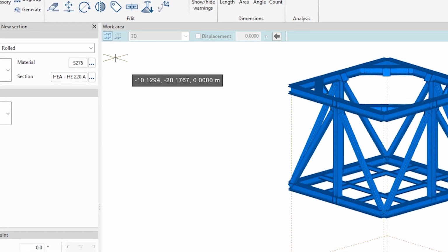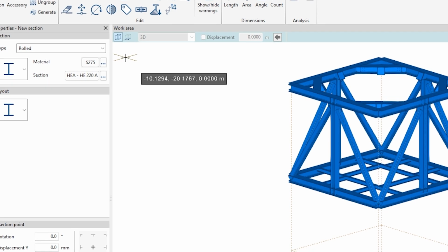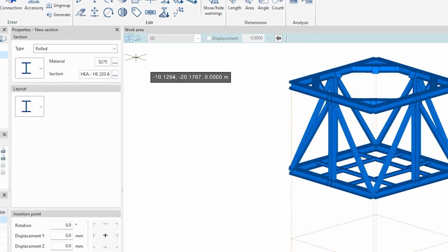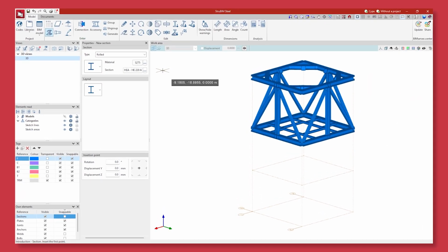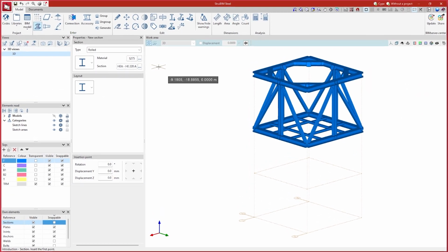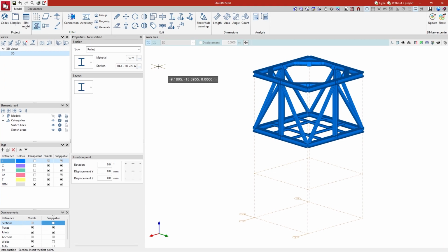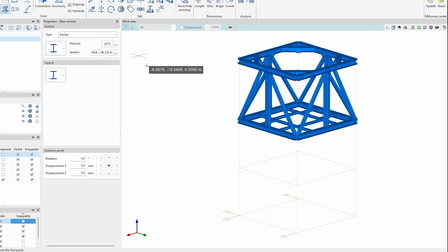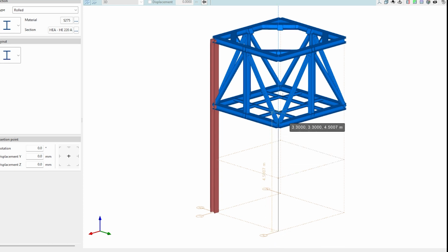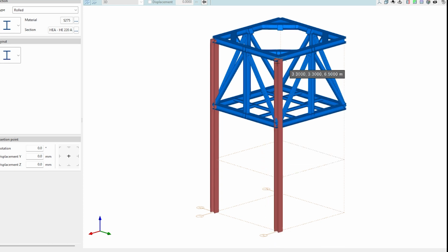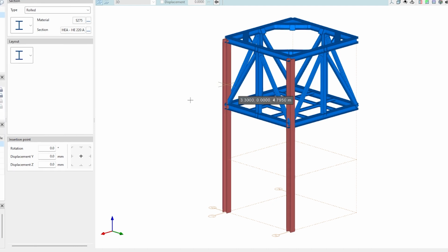The section is defined by its initial and final ends, so to enter it, we must select 2 points on the model with the left mouse button. Several options are available to help us enter these points. For example, we can snap the lines of a previously defined grid. To snap points of other elements already entered in the model, we make sure that these are snappable in the visibility options on the left, and we use the Object Snap option.